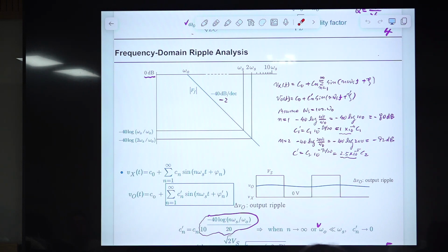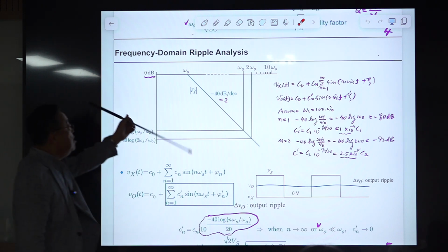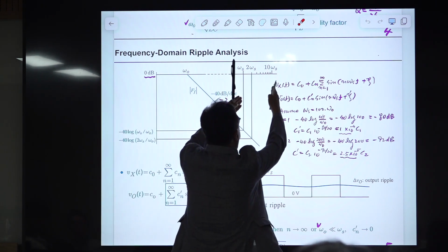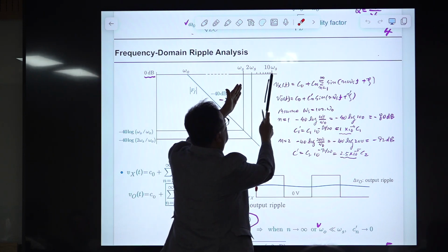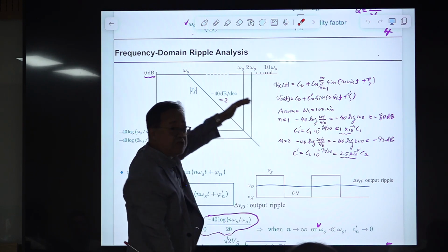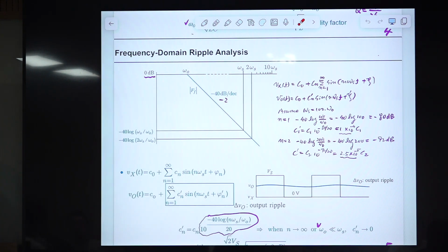This shows the frequency response of a second order system. The x-axis is the frequency. It is a linear scale, and inside of one decade you have a log scale. This is called a semi-log scale, a combination of linear and log scales. The y-axis shown here is the ratio of the magnitude of our voltage divided by the input voltage, which is Vx magnitude, evaluated in dB scale, a log scale.